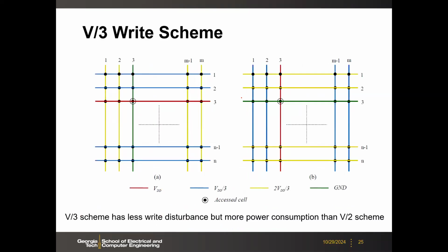So then there's another read scheme that could be used, called the V/3 scheme. Okay. So here, again, this is for bipolar operation. Let's say what you can do to write the data 1 here: you can apply V-write to the selected row, and again you ground the selected column. So here again, you have VW across the cell, which you can write the cell.